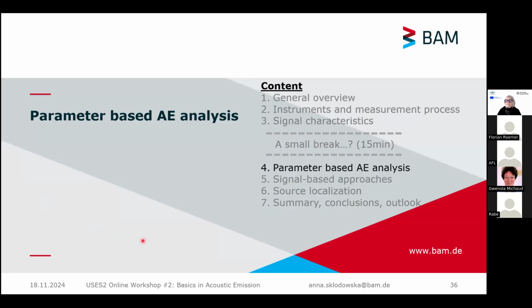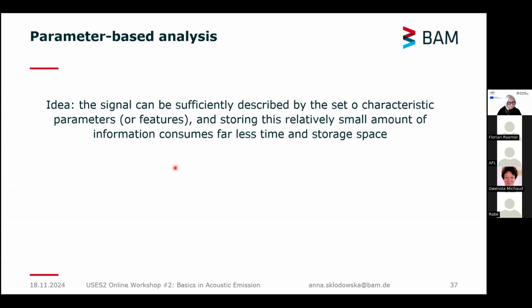So the second part of the presentation, I will start with the parameter-based acoustic emission analysis. The general idea behind the parameter-based analysis is that the signal can be sufficiently described by a set of characteristic parameters, so-called features, and storing the whole waveform is not necessary. We can just store a small amount of information, which consumes less time and less space, and we can still do the analysis of the signal.